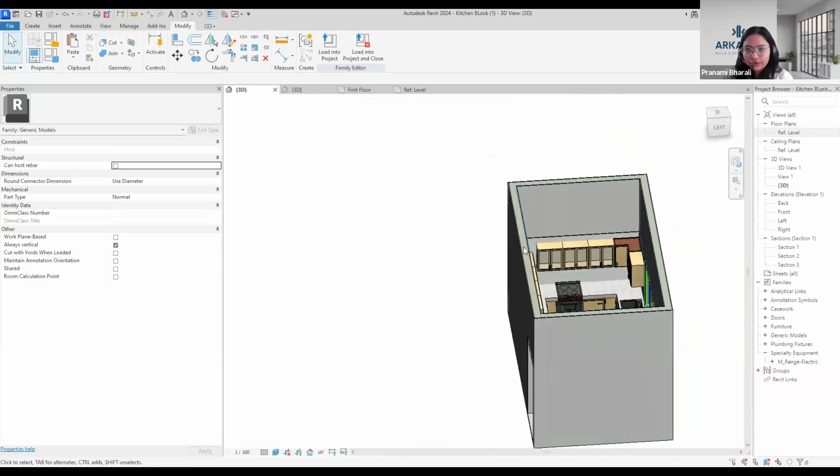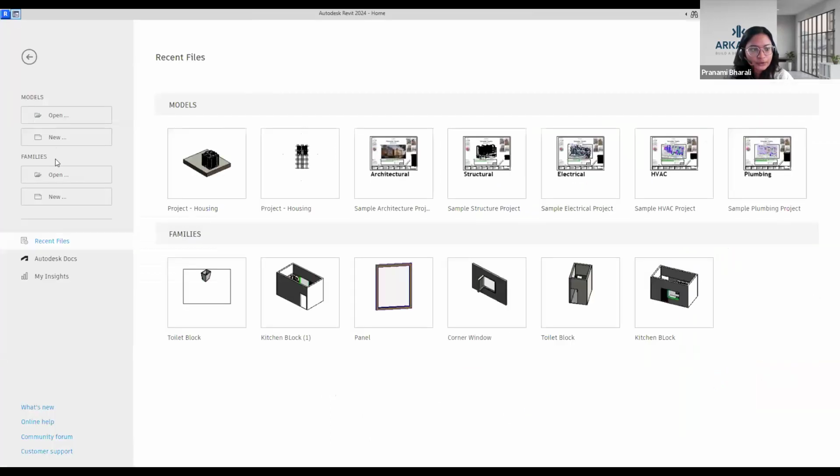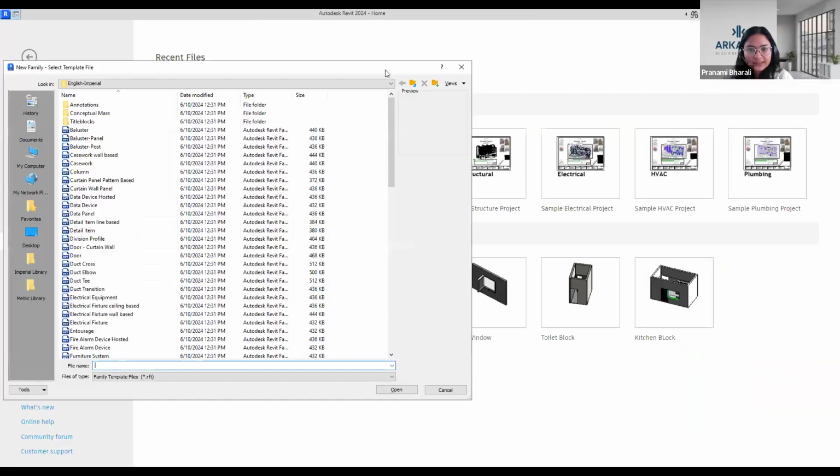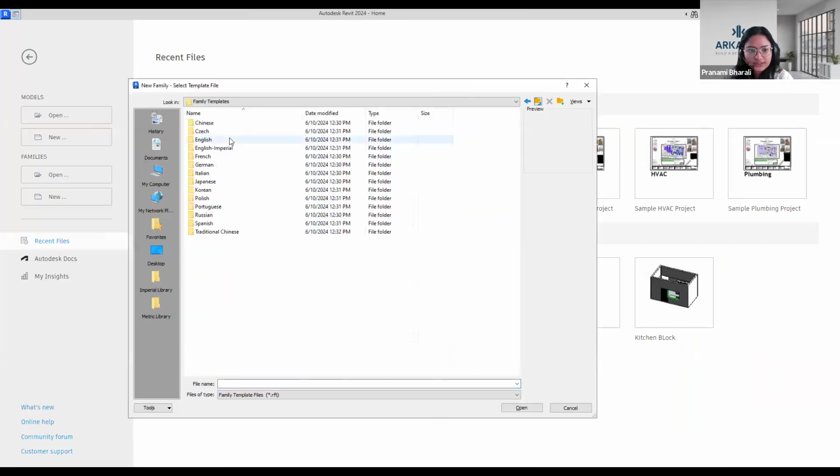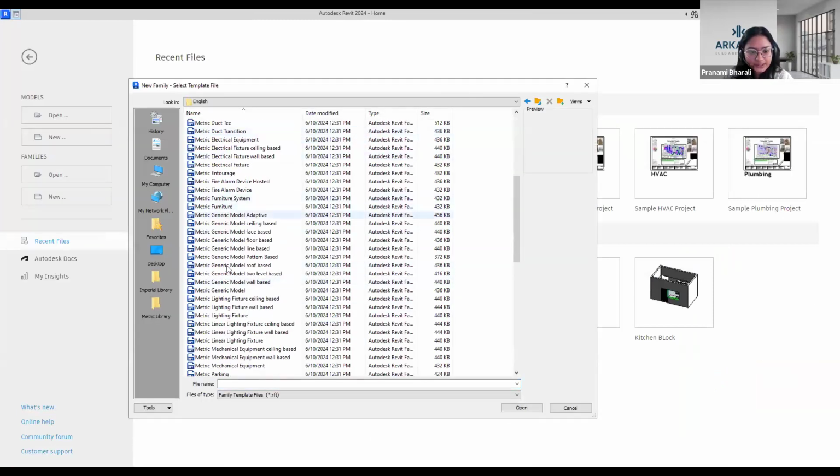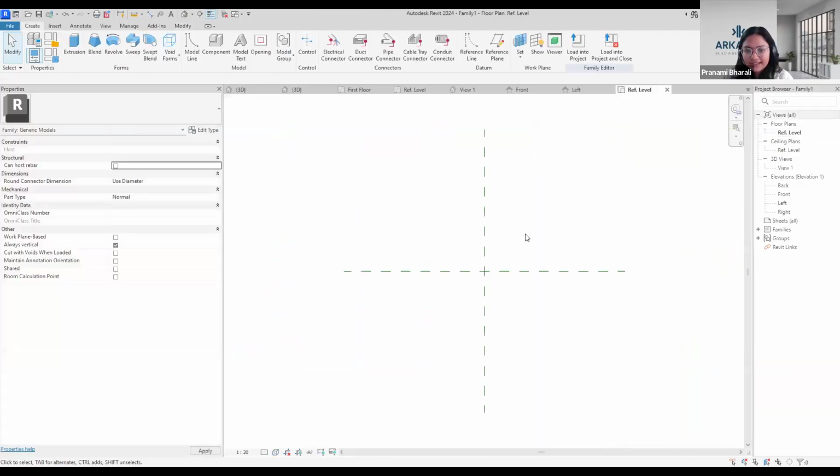If you are a user of Revit, you will know that we have different families in here; these components are called families. I have prepared this in a template called metric generic model. In this template, you can design your whole block. It is up to you what you take, but in my case, I have taken the kitchen block, and I have designed it using different kinds of extrusion forms and everything. This is placed here along with the plaster layer and different components.